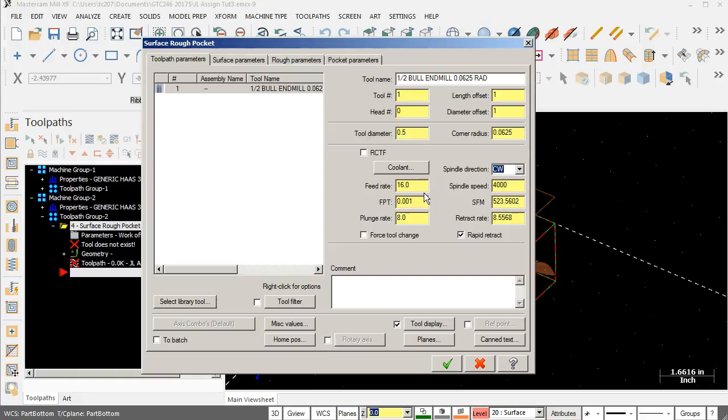Aluminum, sure, if I had a 12,000 RPM spindle, I would probably still be running the 1/2 inch tool somewhere around 8,000 or 9,000 RPM, but my feed rate would be comparably faster, up around 60 to 80, maybe 90 inches a minute, depending on how aggressive, how much cut it was going to have to take, and what I was looking at as depth of cut.